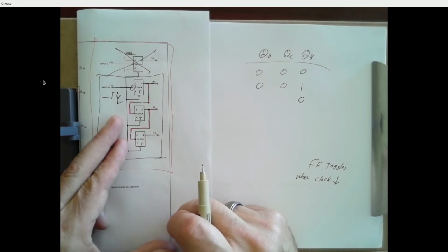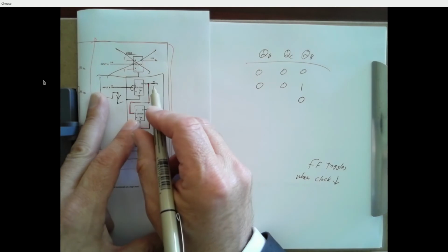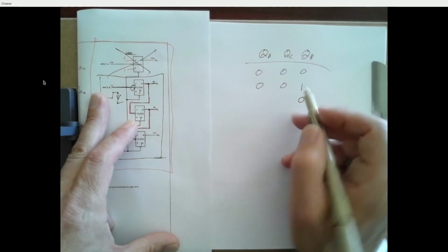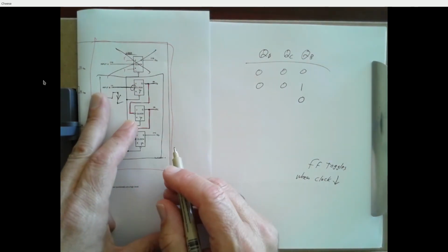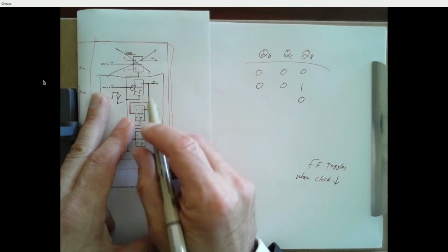The B going into C. So whatever the value, in this case, that's J and K. J and K are 1. Okay, that's what's making this thing act like a T flip-flop. The only thing that's being changed here is the clock. And the clock is whatever this output QB is.